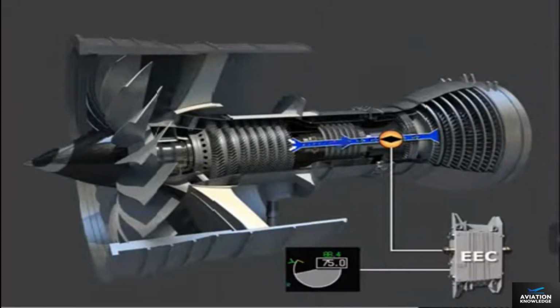Failure of the SASV in the open position could lead to an abnormally high temperature in the system and overheating of the engine bearings. If the valve fails open, the maximum thrust indication is reduced on the TPR. If this occurs above 400 feet AGL, thrust is automatically reduced to a safe limit, and the thrust command arc on the TPR gauge displays amber.